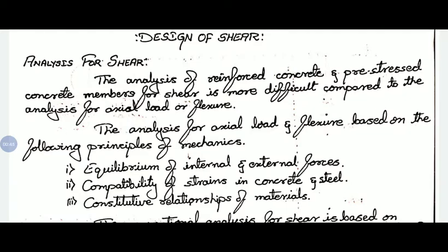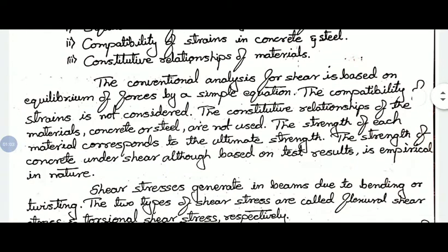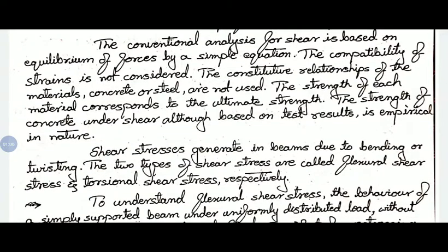In analysis, we will consider the shear stress based on a few principles of mechanics. One is equilibrium of internal and external forces, compatibility of strains in concrete and steel, and constitutive relationships of materials. If we analyze any member by conventional analysis, meaning with respect to RCC, we'll consider only simple equilibrium equations like sigma Fx, sigma Fy and moment.